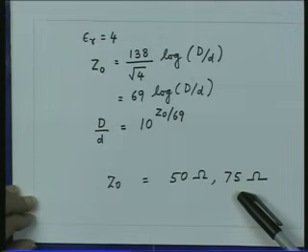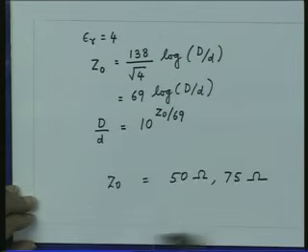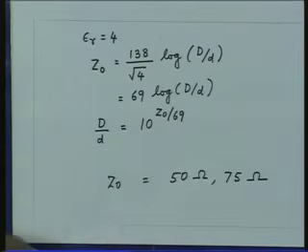So, from the compatibility point of view of the impedances, whenever we use the cable for antennas, we use a cable having characteristic impedance 75 ohms. However, for most other applications or high frequency equipment, the impedance has been almost standardized to 50 ohms.